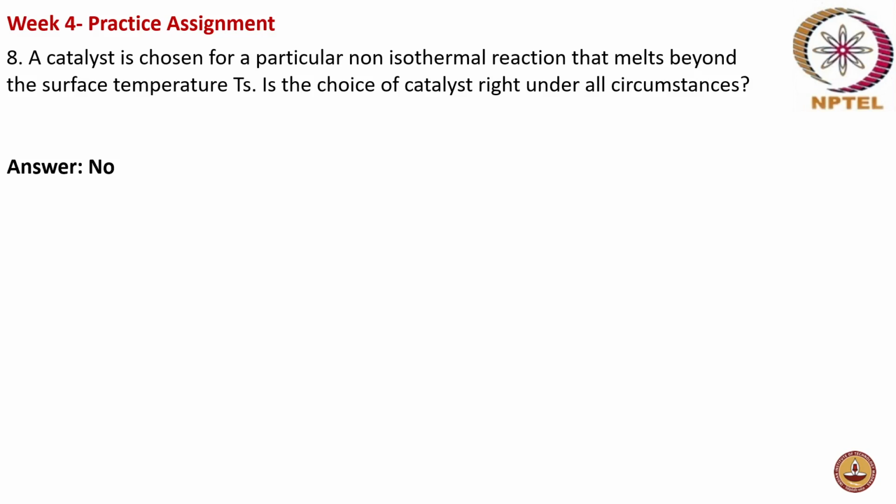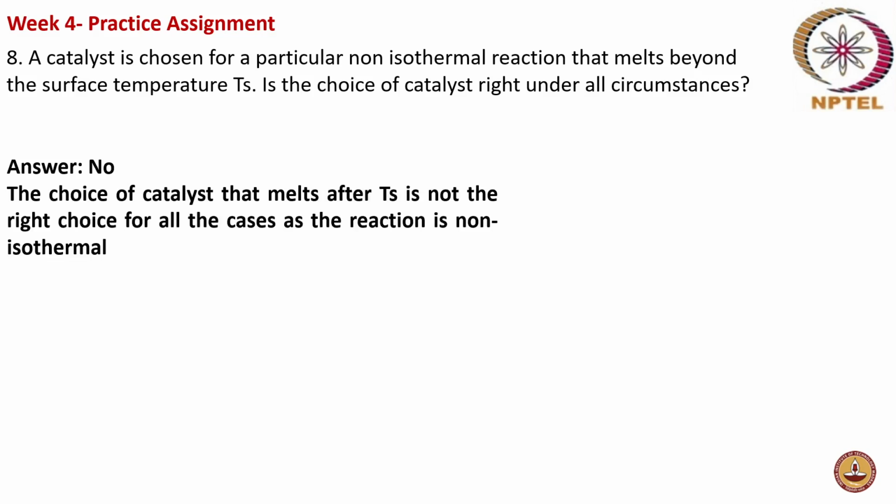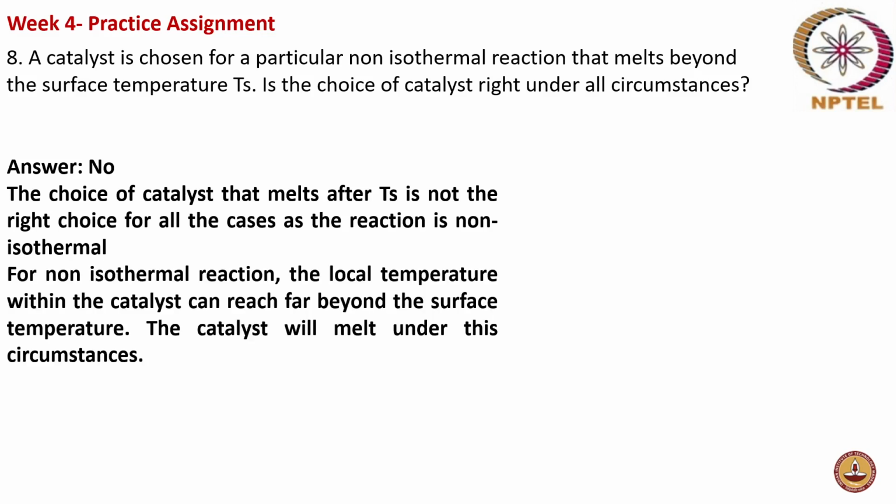The answer is no, we cannot choose this catalyst which melts beyond the surface temperature of the reaction, the catalyst surface temperature. Why? Because a catalyst that melts after Ts is not the right choice for all cases of non-isothermal reaction. If it is an isothermal reaction, then the temperature is not going to change much, so Ts will be maintained. Whereas for a non-isothermal reaction, the local temperature within the catalyst can reach far beyond the surface temperature.